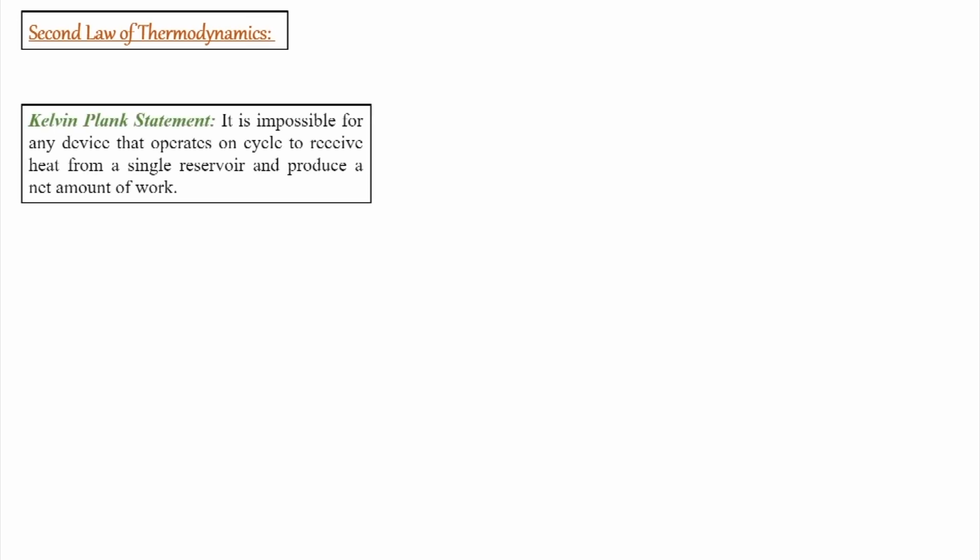Then we have the second law of thermodynamics. Basically it has two statements, and the first is the Kelvin-Planck statement, which states that it is impossible for any device that operates on a cycle to receive heat from a single reservoir and produce a net amount of work. So practically, if we have a thermal